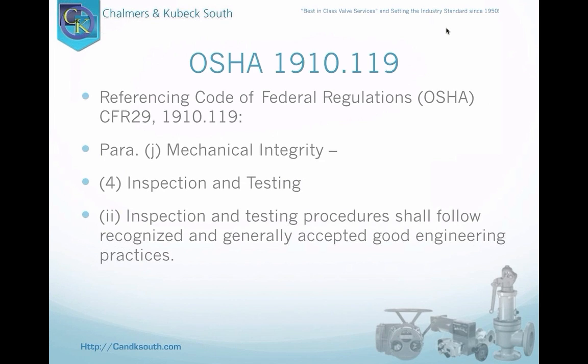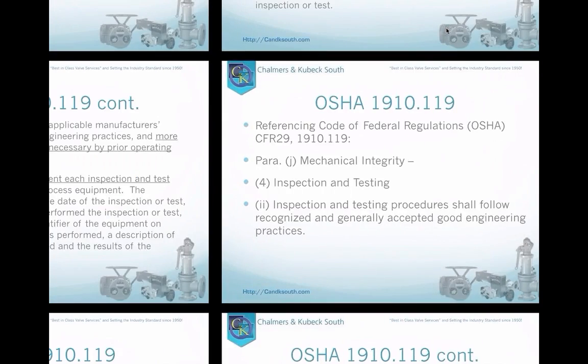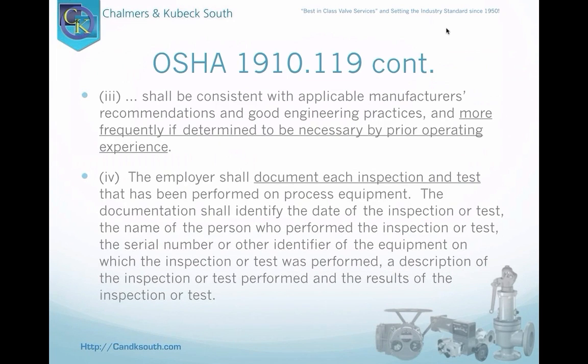The regulation specifically talks about mechanical integrity of all your equipment, as well as the inspection and testing procedures. Not only the frequency, but exactly how those procedures are done to make sure they are in accordance with generally accepted good engineering practices, which is usually dictated by the manufacturer. It shall be consistent, as it mentions here, with manufacturer's recommendations, and more frequently if determined to be necessary by prior operating experience. And that's a key thing that I've underlined here, because you have to have that experience, but where do you have documentation to draw from to back you up when you make those decisions, whether it be to increase or decrease the frequency? ValveKeep provides that for you.